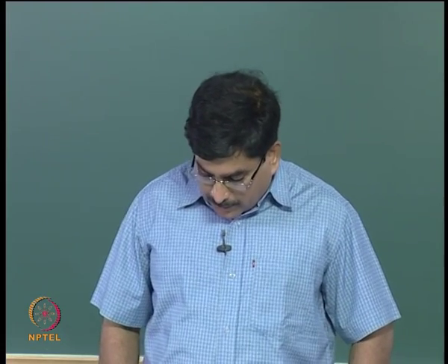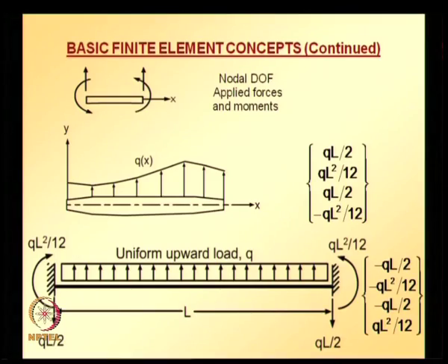So what is the physical interpretation? The finite element equivalent nodal loads are simply fixed end forces with sign reversed.